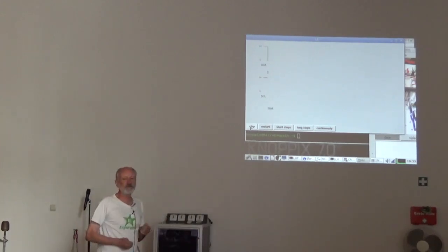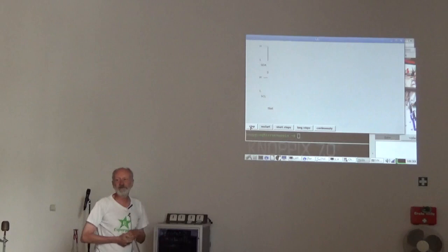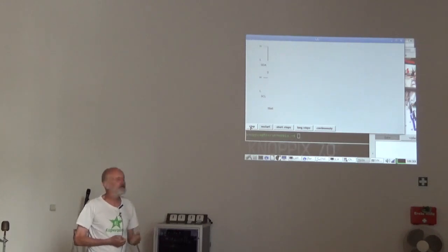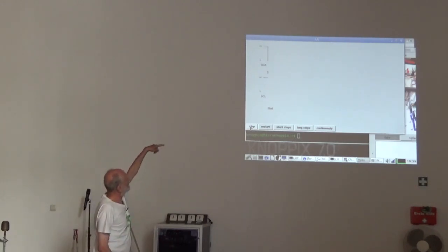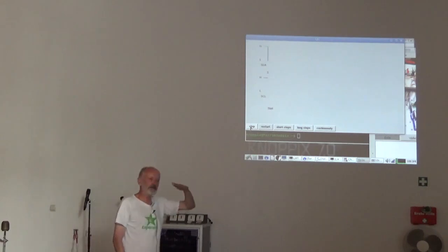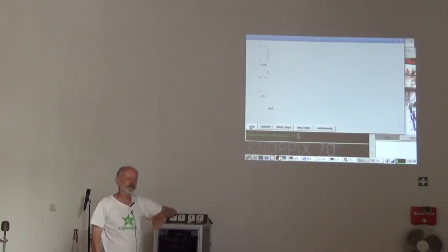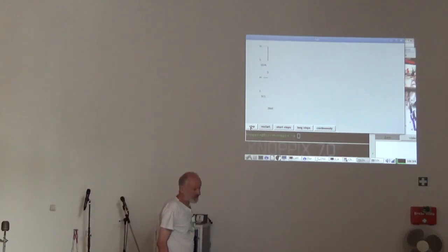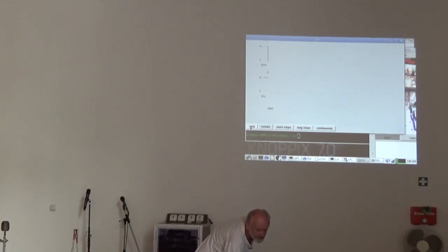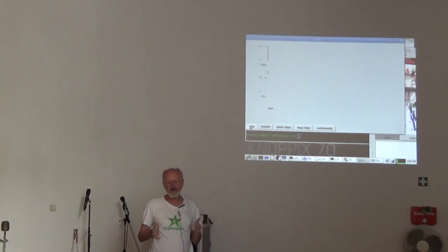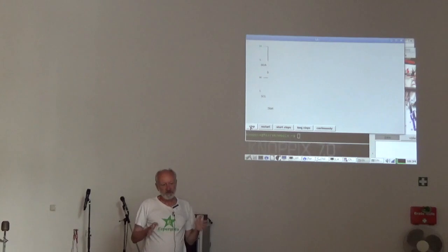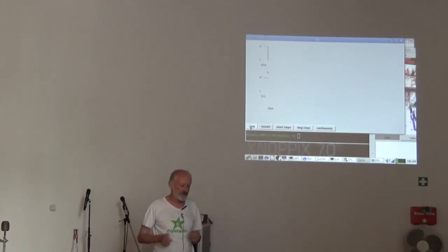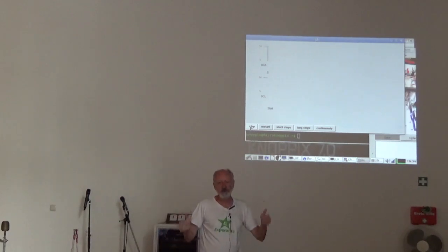Also, one state of the I2C bus is that you send a start command, and the start command is that while the SCL level is high, the SDA will go down. This makes a start, and then the next affair is that you must address a chip on the I2C bus and send 8 bits.